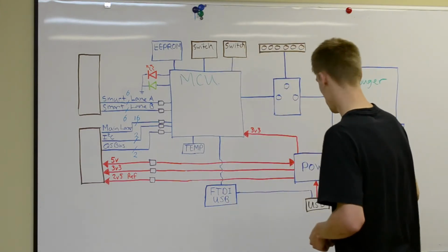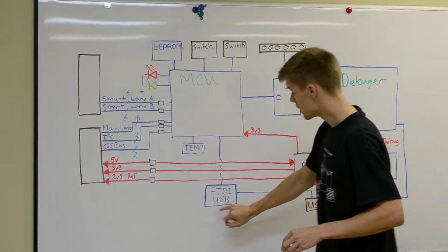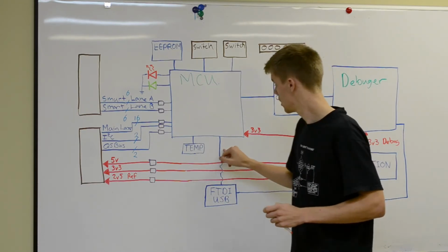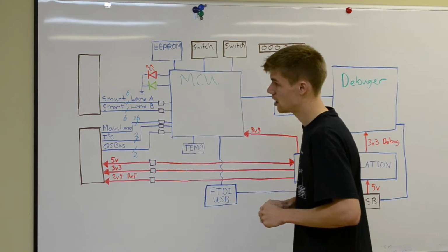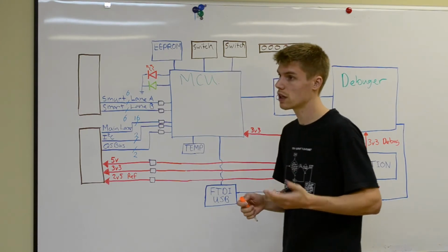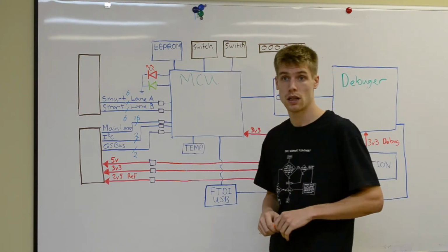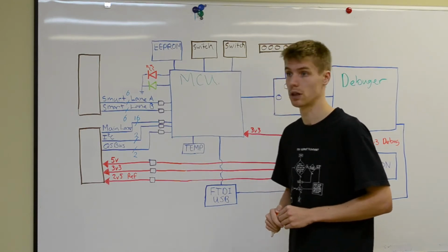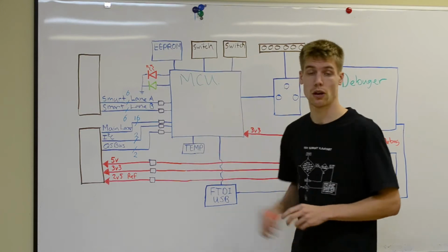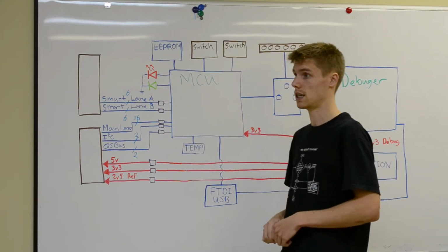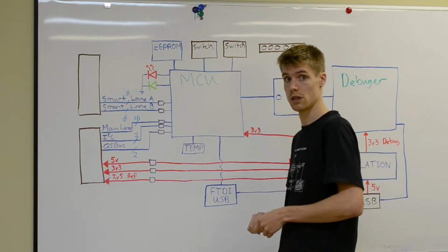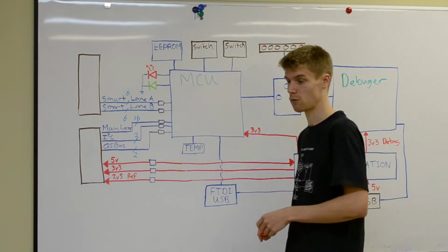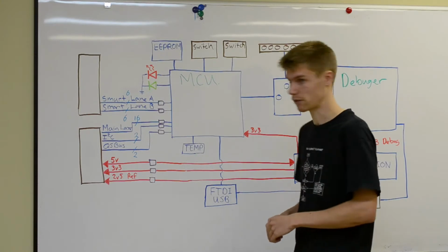So, furthermore, the FTDI chip has a parallel interface. Realistically, you can get about 1 megabyte per second. Now, obviously, in PC terms, that's not very fast, but considering this is a 16 megahertz, 16-bit processor, it is incredibly fast for the embedded world. If you see the data coming in through a serial line at 1 megabyte per second, it's impressive.